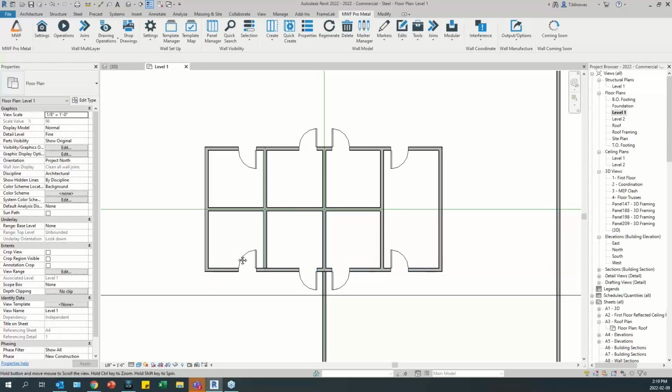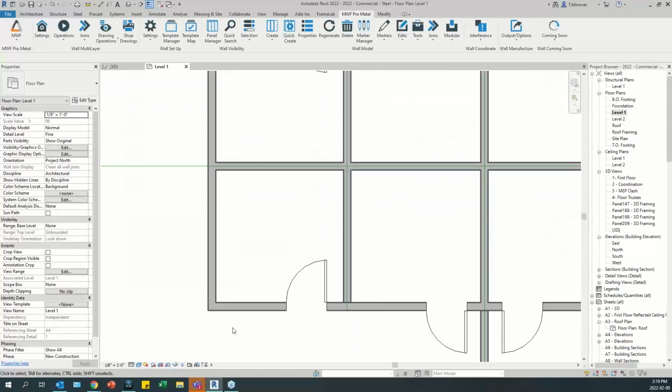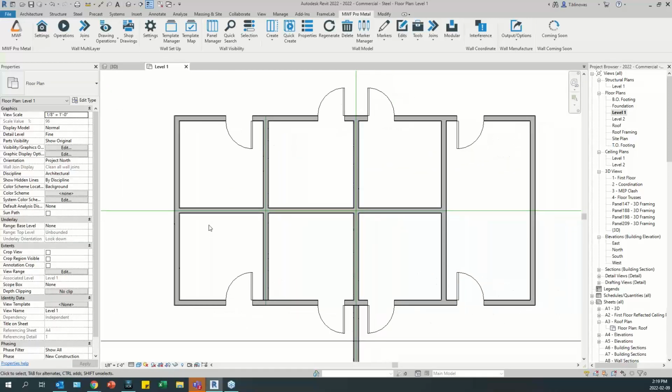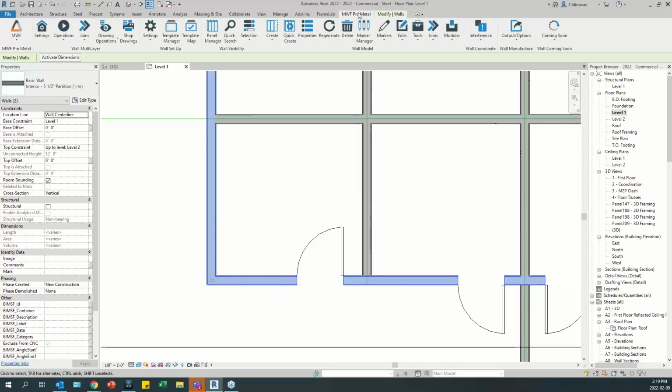And again, just like when we do in the templates, you can go to the side, identify the corner types that you have and recreate them, so you don't do that in the project itself. But here, because it's just an exercise, it's a very simple project, I'm going to go ahead, and the first corner that I identify here is my 90 degrees corner. So the process will be very similar to manually adding the join, but this time we are creating the rule. We're not adding the joins just yet. So I select this corner. I come here to joins, and I'm going to click on create auto join rule.